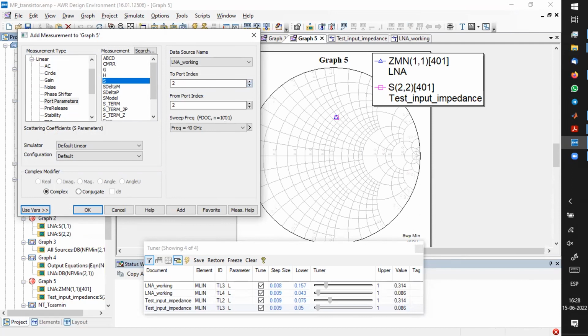Where are we now? I didn't follow. Are we at the output of the LNA? The output. Okay, the LNA working now has the input matching network, and you will add the transistor there now. Now the first transistor is matched, right? So we add the transistor to the input matching network. See the second formula. Exactly. Now we need to match for the second transistor.